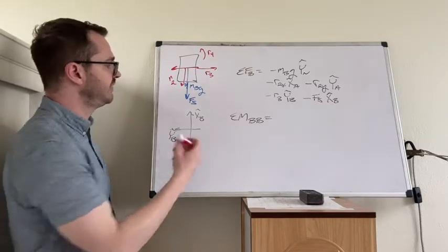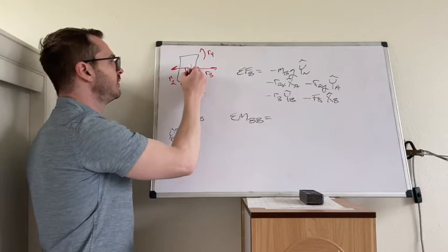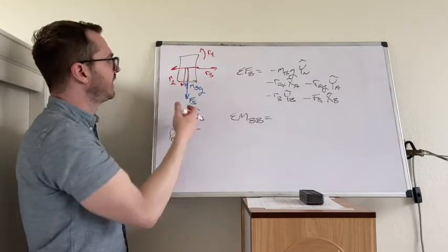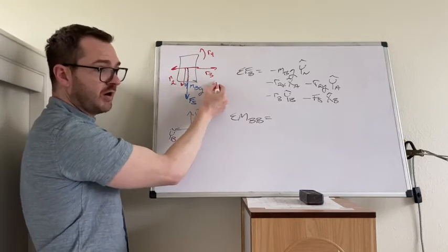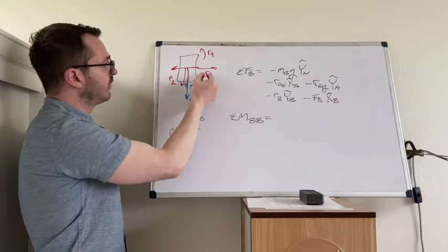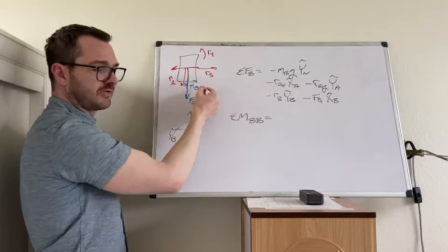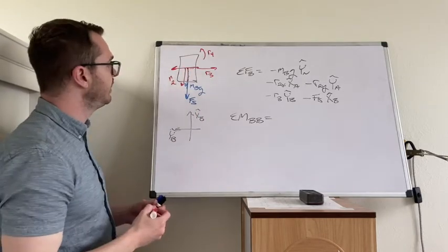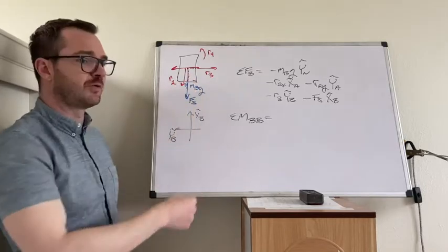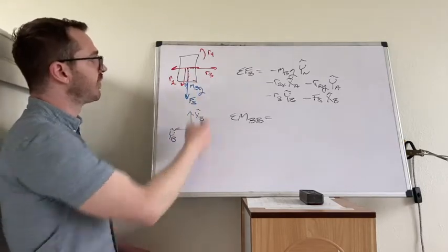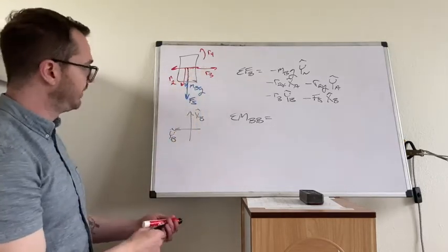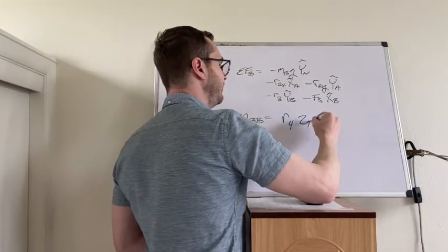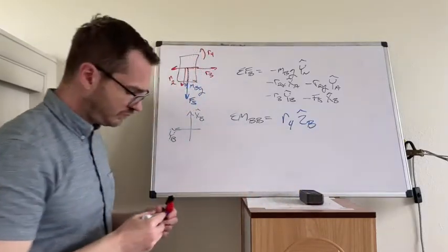If we attach the spring force along that same line that contains the center of mass, and if we model this normal force as on the center, the geometric center of this plate, that puts it right in line with the center of mass as well. None of these forces create any moments. The only moment then in the problem is just this reaction moment R4. So R4 in the ZB.